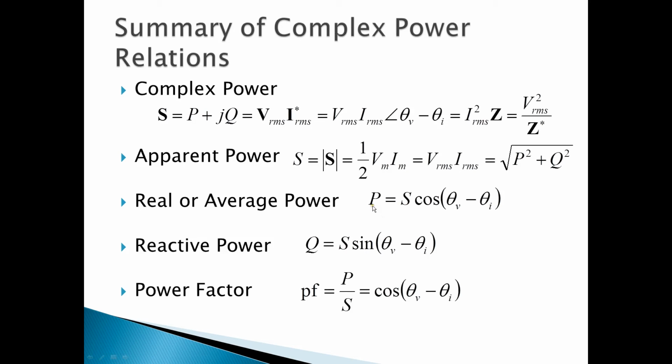Again, real power and reactive power are calculated by these relationships here. And the power factor tells us about the angular difference, the phase angle difference between the voltage and the current through an element, and is also related to the apparent power and the real power of the system.